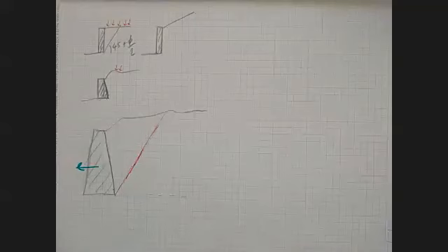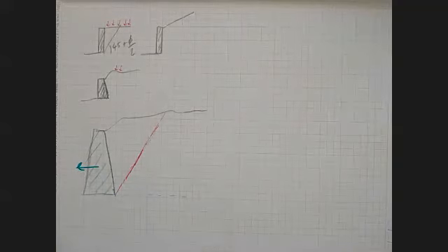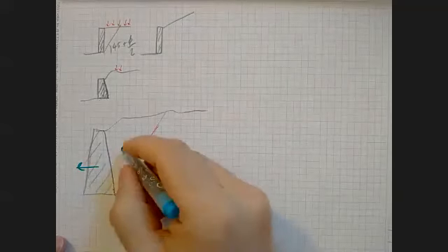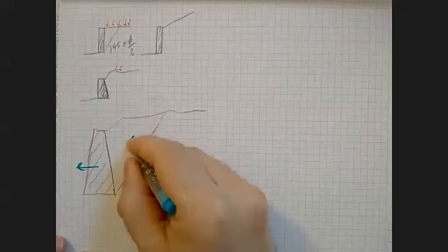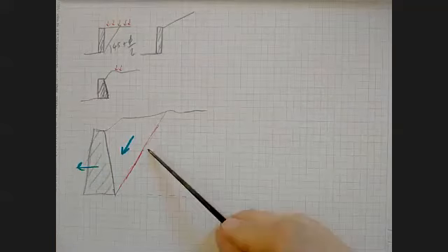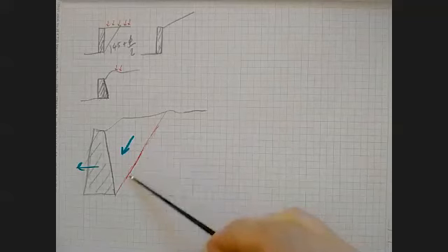As this wall moves to the left, the failure happens by this wedge moving along the shear plane, and as you move along this shear plane, you are making shear failure according to Coulomb's strength equation.